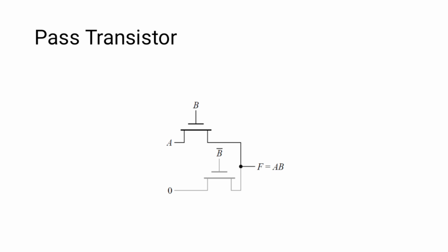This analogy works in multiplexer logic, so pass transistor logic is mostly used in multiplexer based designs. We can reduce the number of transistors over here.